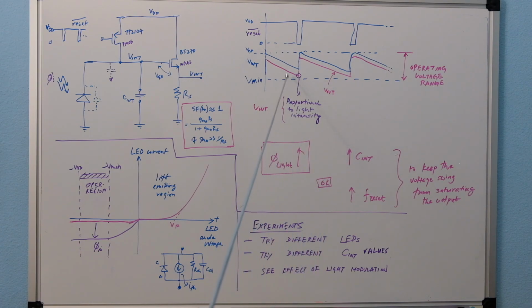down by that amount. The only problem is if you run this, discharge this cap completely, then you effectively turn off this device. So you want to operate at some voltage, several volts above the minimum threshold voltage for this thing. So in this particular example, I'm keeping this Vmin around, I think, 4 or 5 volts just to be safe. So you won't discharge it beyond this. You'll immediately reset by the time it gets there.